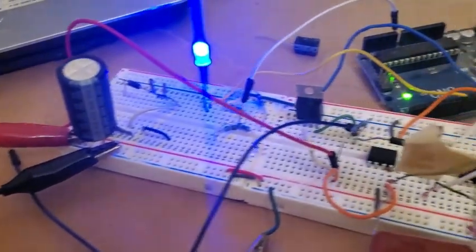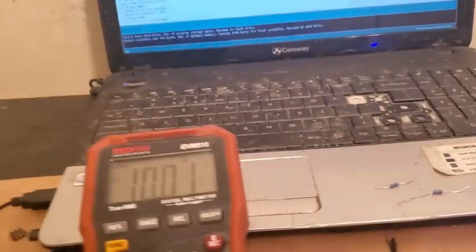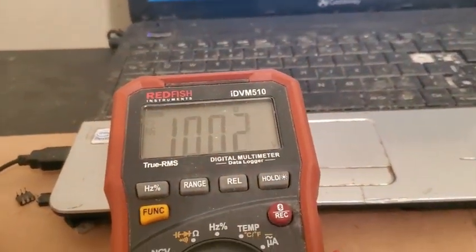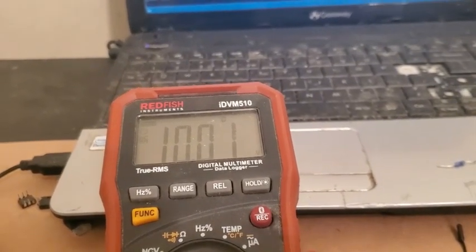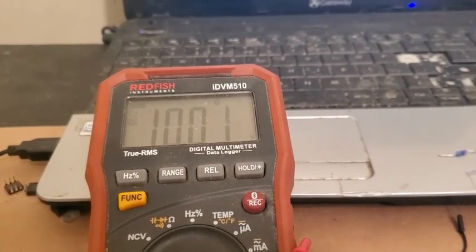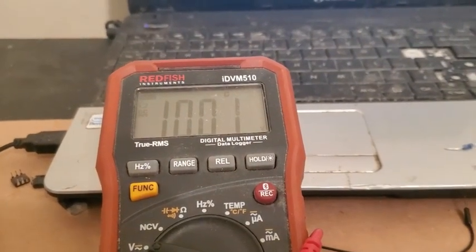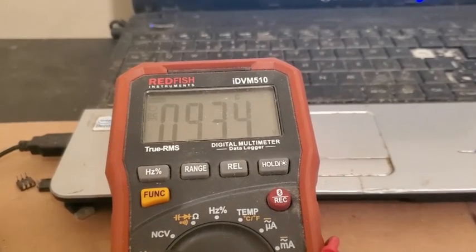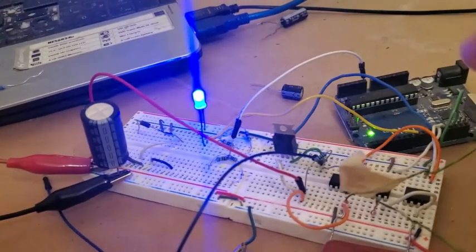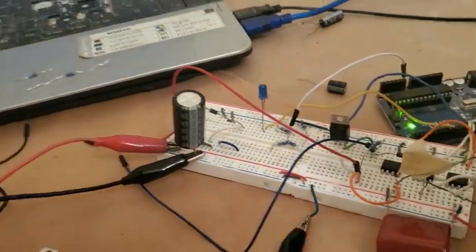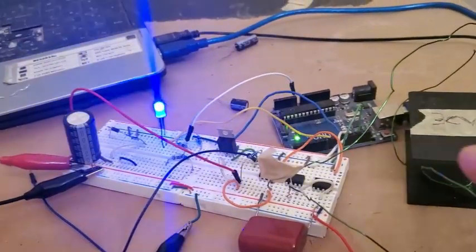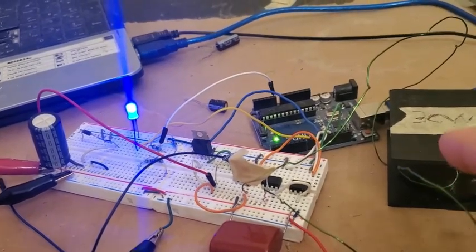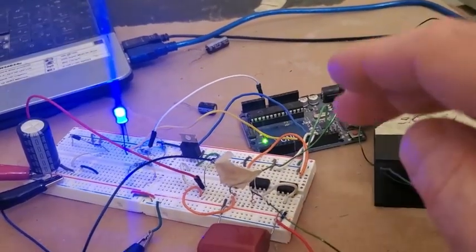And keep in mind, the number of pulses is the exact same. The pulse duration is the exact same. And what does it discharge to now? When it was loaded with the cap, this darn thing drifts a little, it went to 9.33, unloaded 9.27. Now loaded with a 100 ohm resistor, 9.33, 9.34. And if you start putting a lot of resistance across there, like 10K, it starts going back down towards 9.28, 9.27. So that's pretty interesting, that the more you load it, the less power it draws.